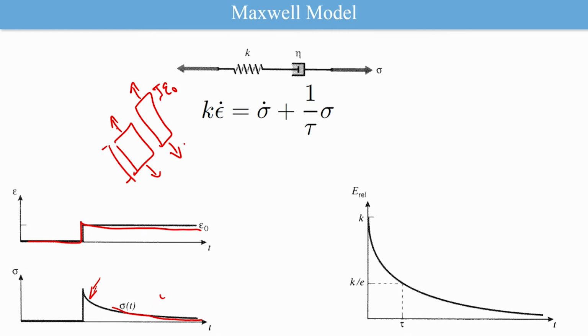So, the same expression using this constitutive equation we will try to solve how it works. Now, in this kind of strain that we applied, after we apply the strain there is no more strain rate, or there is no change in strain after we apply the constant strain epsilon 0. So what happens is the epsilon dot term actually becomes 0.